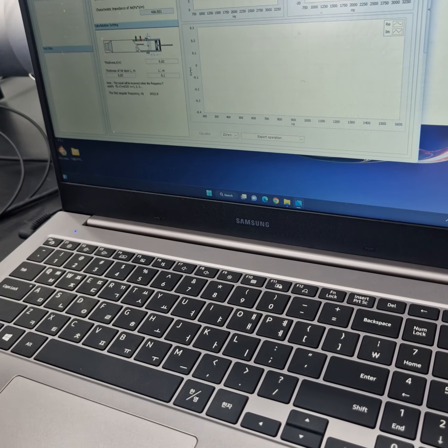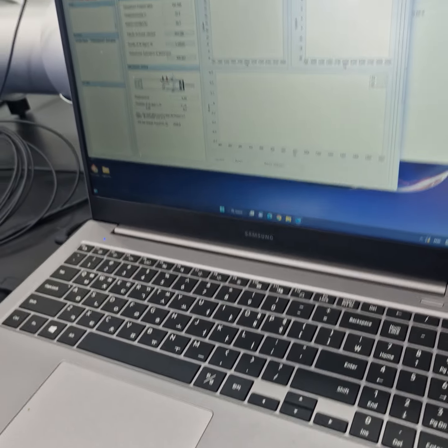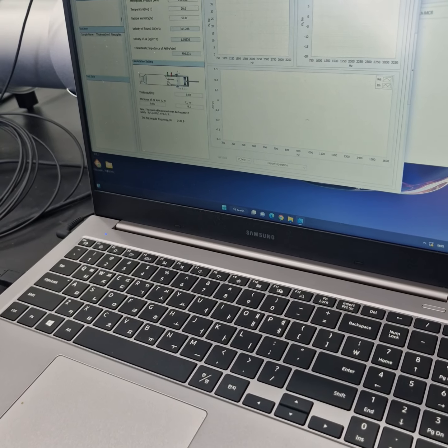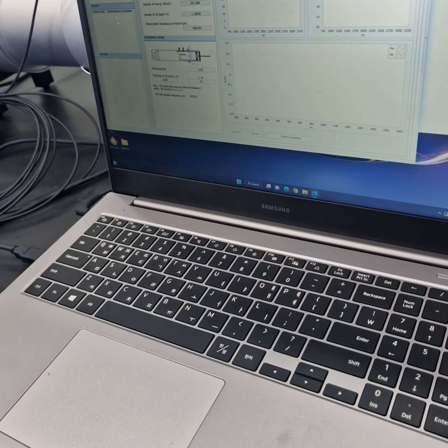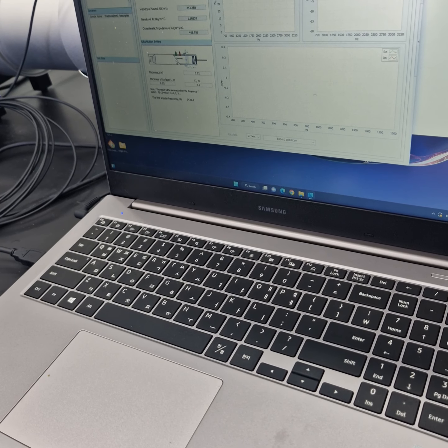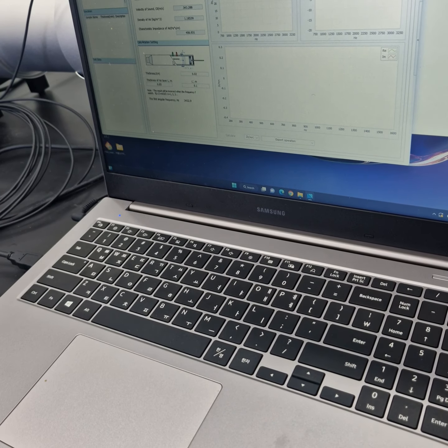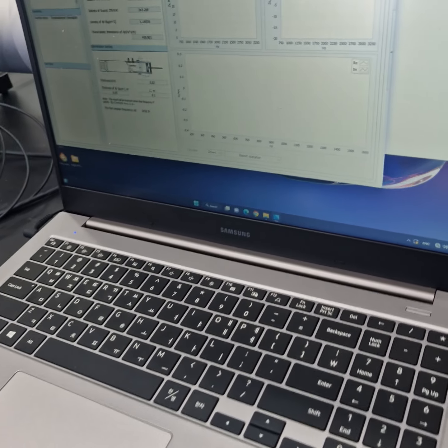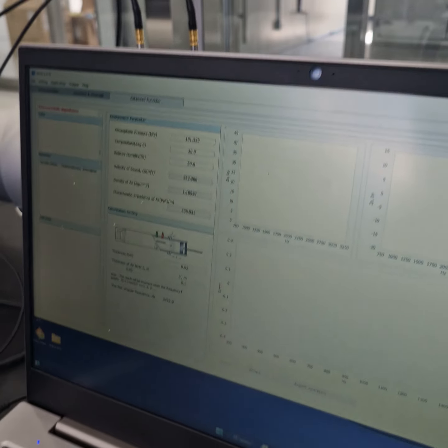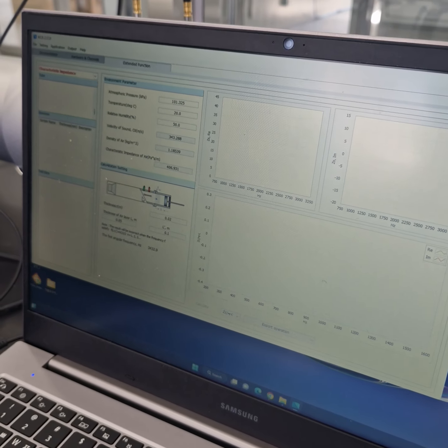If you are testing transmission loss and go further into investigating the acoustic material properties, you will encounter two properties: characteristic impedance and complex wave numbers.